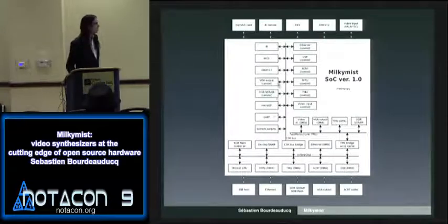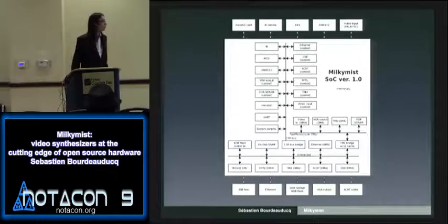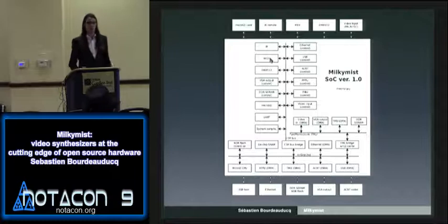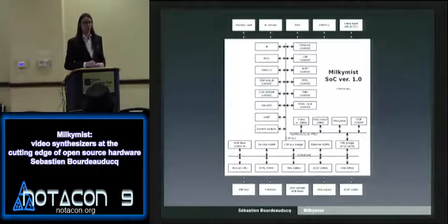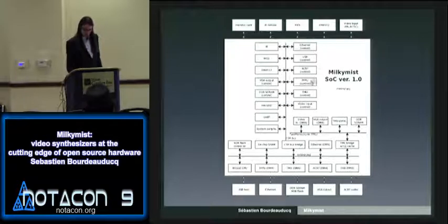It includes basic peripherals like USB, a serial port, GPIO, basically what you expect of a microcontroller. And then you have more specialized peripherals, like, for example, an audio controller, infrared, integrated MIDI, integrated DMX. The DMX is a protocol for controlling stage lights. And I'll get back to that a bit later, why we have such weird stuff integrated in the system on chip. We also have a video input controller that takes